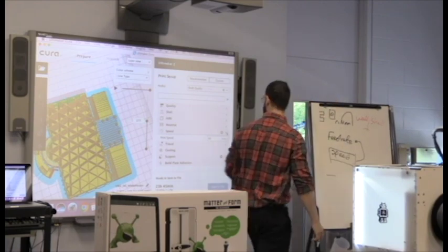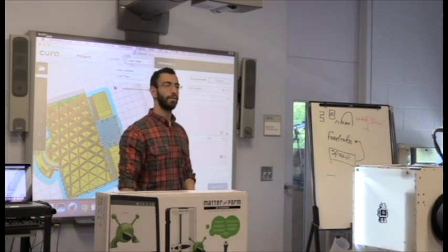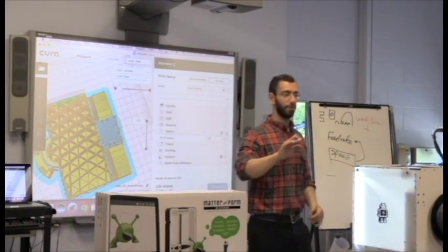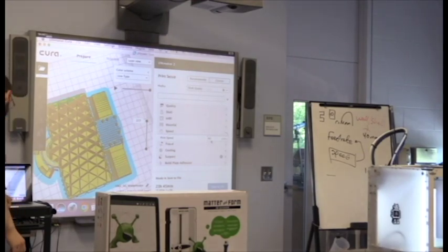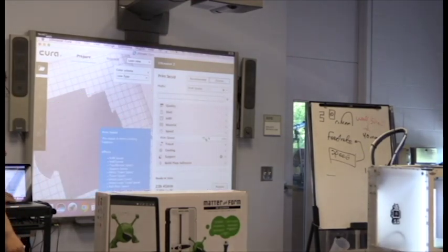Okay, right now this is 60 millimeters per second. That's kind of the average for this printer. That's actually kind of fast. For a while, but we're going to print this soon, hopefully. So usually just adjust this to 40. It'll standard be 60. Just adjust it to 40. That will increase the time.